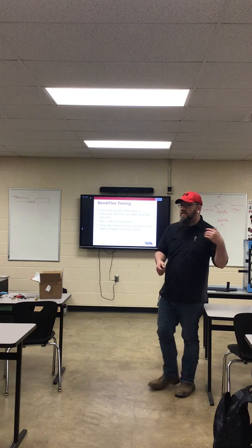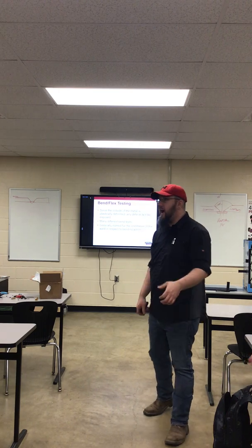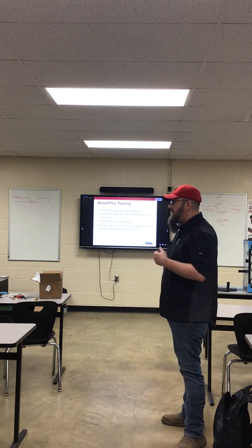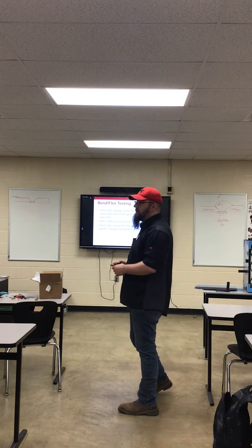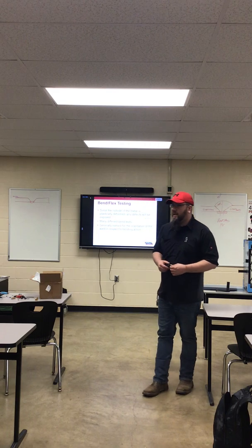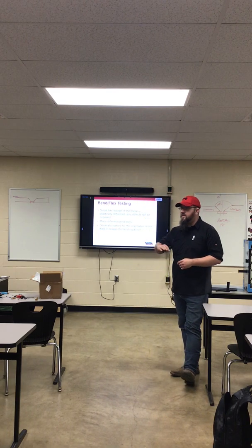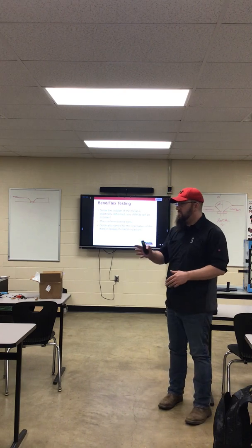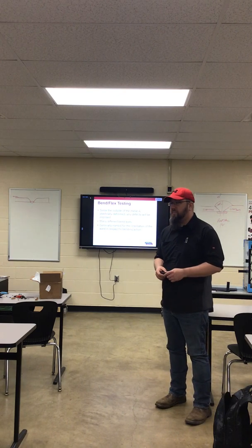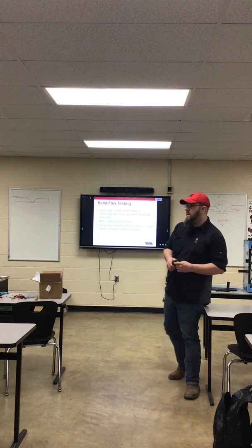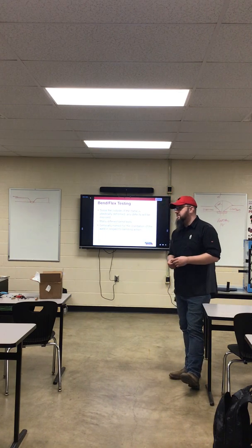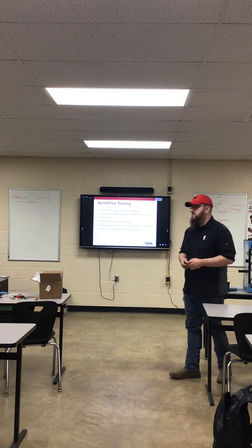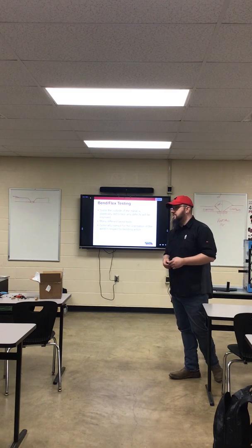Can we discuss some defects? Especially in our hot rolled steel. What do you notice when you start grinding on it, trying to get it down to a proper finish? Is it pitted? Is there any pitting in the surface of it? Sometimes, yeah. Depending on quality of the steel, where it comes from. What else have we noticed about hot rolled? Typically it's a little bit thicker than cold roll, it expands a little. Okay.